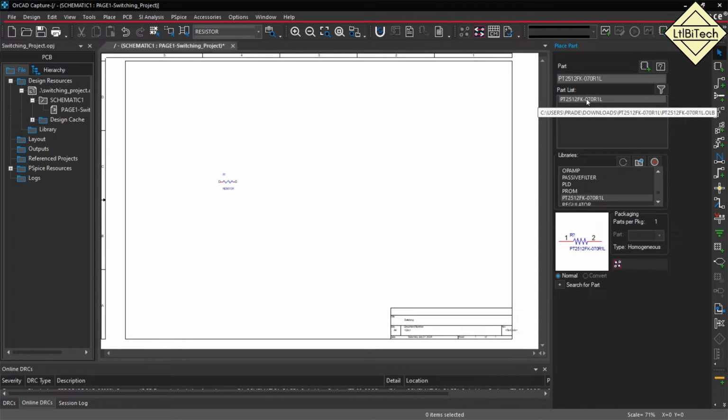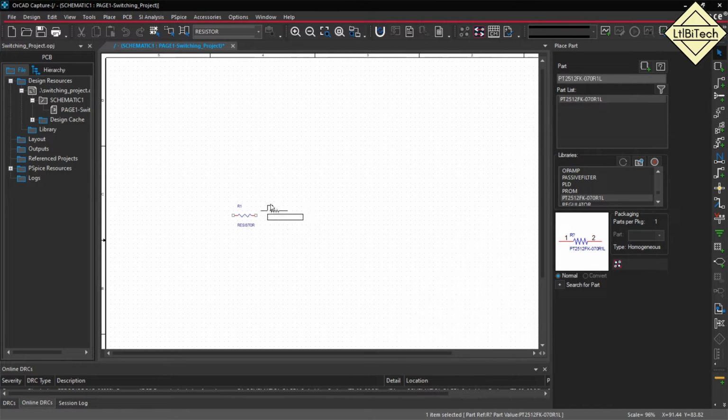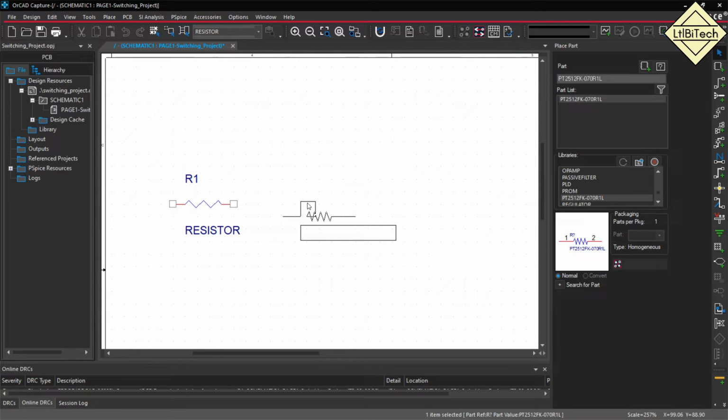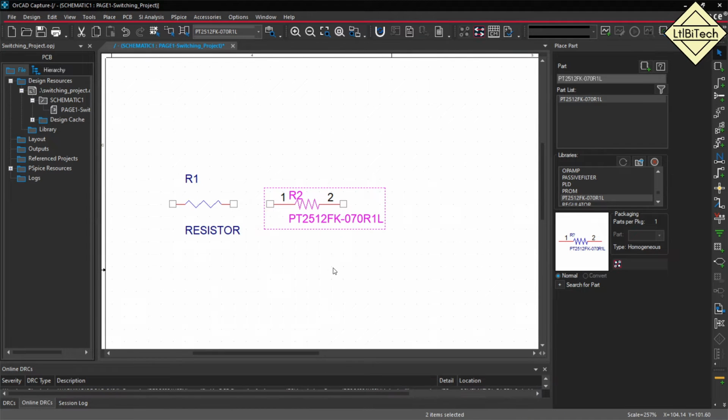You can double click on this component and you can bring that particular symbol inside the schematic page. So this is how we are downloading the library from third party websites and locating that in your library area, and you can use that. The first one we have taken from the existing library. The second one we downloaded from the internet and located here. The third option is you need to create on your own.